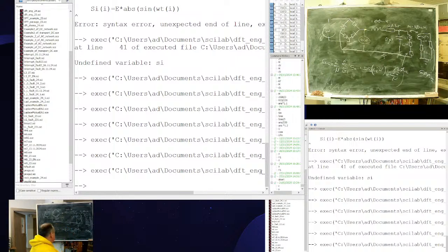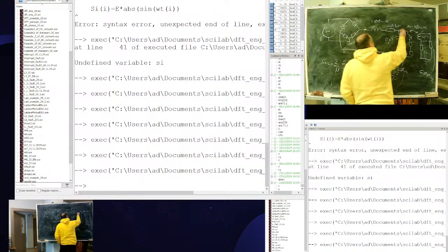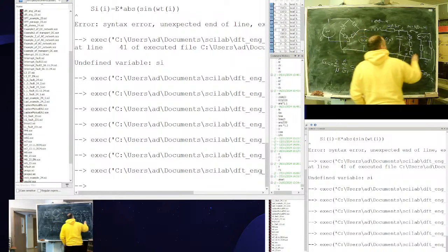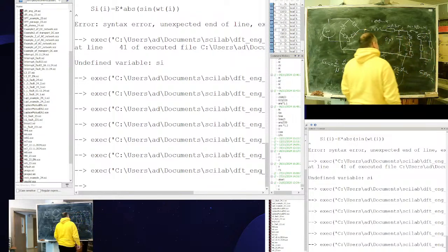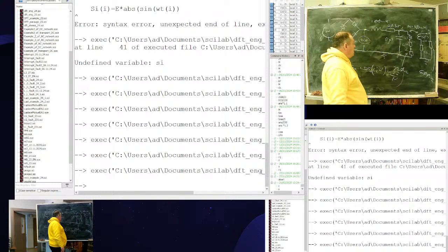And the first thing I do, I need to set numbers for nodes and branches. This will be node 1, this can be node 2, and this can be node 3. I set nodes at the points where I can measure voltage, where it will be possible to attach a scope. Ground, the base node, does not need a number.